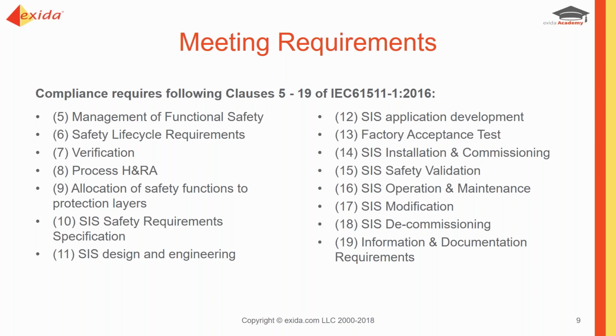And then clause 14 covers installation and commissioning. How are we going to install it? How are we going to commission it? And once we've done that, then we have to validate. In other words, we have to make sure that the SIS, as it's installed and commissioned with its CFCs, meet all the requirements of the SRS, including timing. So we need to be able to prove that.